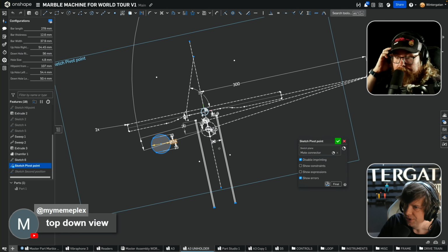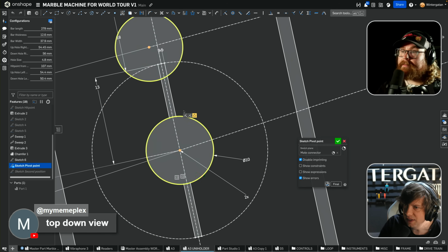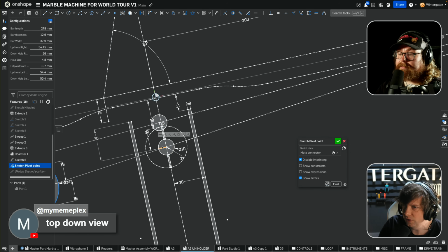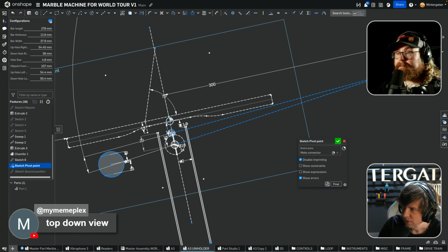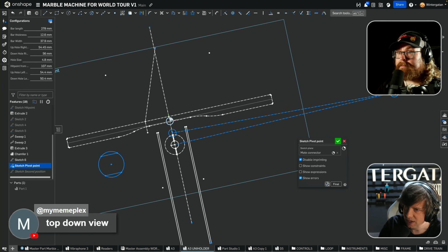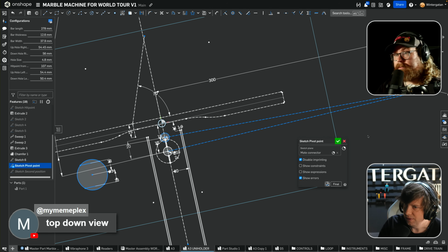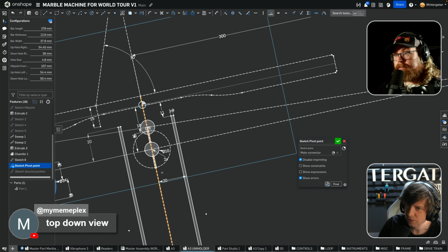That's very useful. I think I made this perpendicular to the plate, but we want as little movement as possible around this point, so we should make it perpendicular to this point. So instead of this line to the pivot, if we pull this down, we can already see here how this goes more straight up. I think I should make this line that the pattern created, Shift L, perpendicular to the center line of the tube.